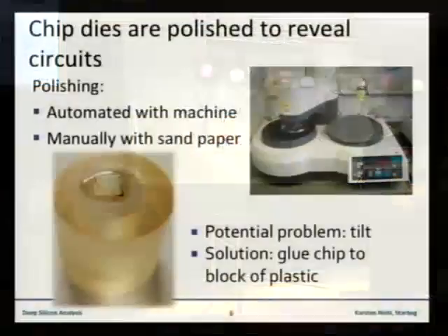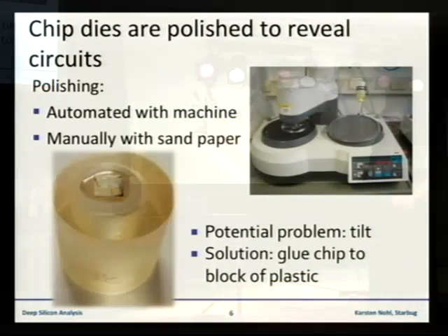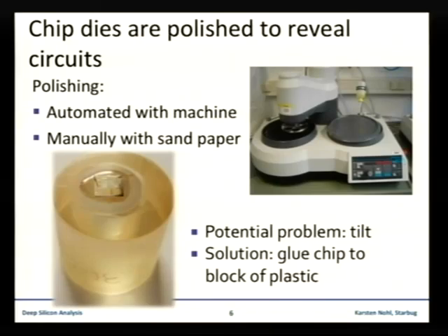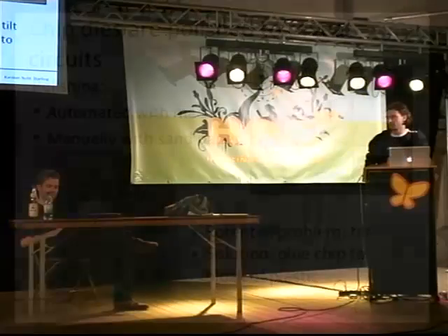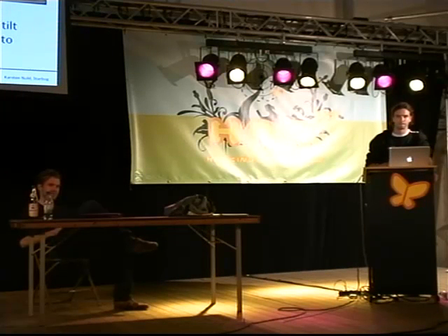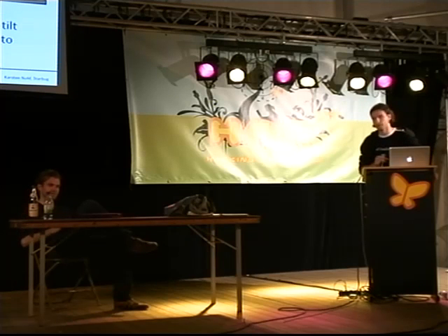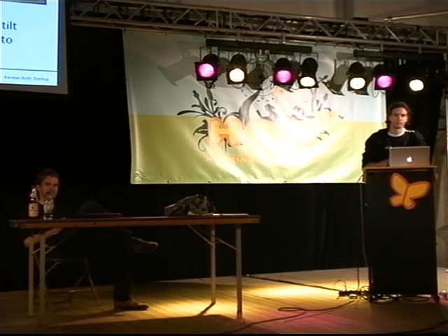Let's point out, though, that this polishing machine is absolutely not necessary. Nice to have, but we have been doing fine with the finest sandpaper and a vibrating surface at my university. So this is deluxe equipment. You can definitely do with less fancy stuff. We started with polishing equipment from an optical fiber laboratory. Everything below 1 micron grain size of the polishing liquid or polishing paper should be fine.